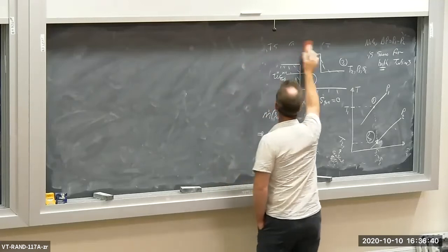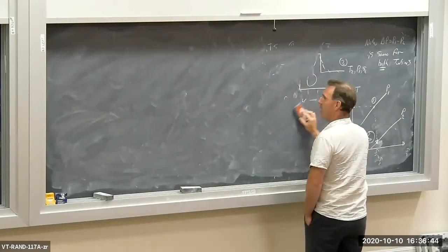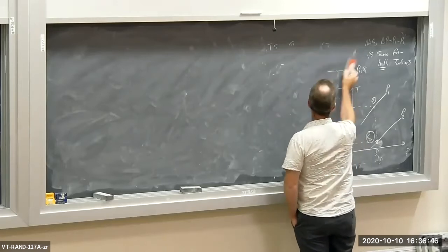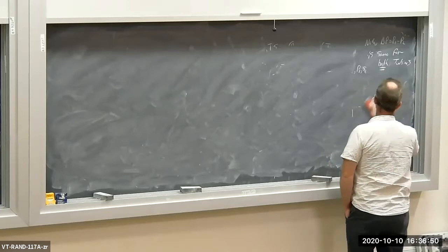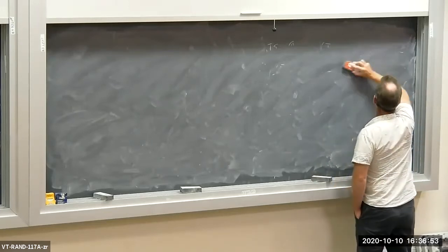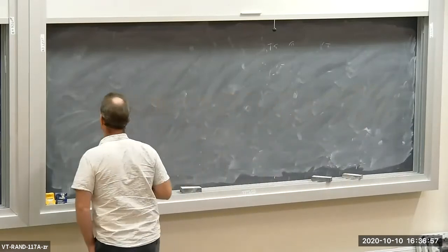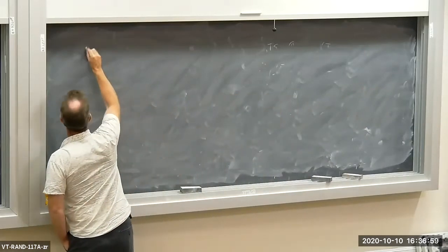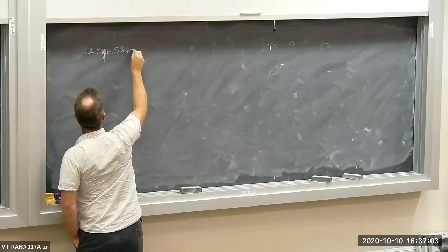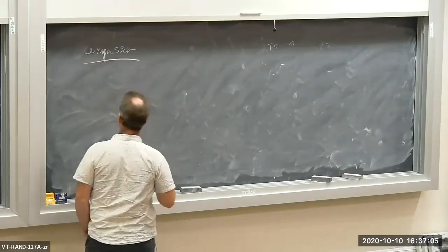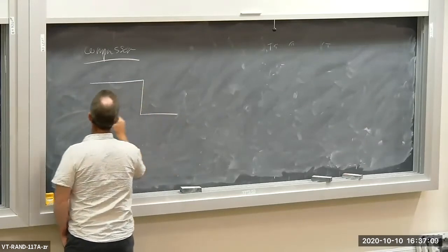So the reversible compressor is the power-consuming device which consumes the least power between two pressure limits. So we can go through the same thing for a compressor, but we end up with different definitions and a slightly different TS diagram. So for a compressor, this will be a work or power consuming device.